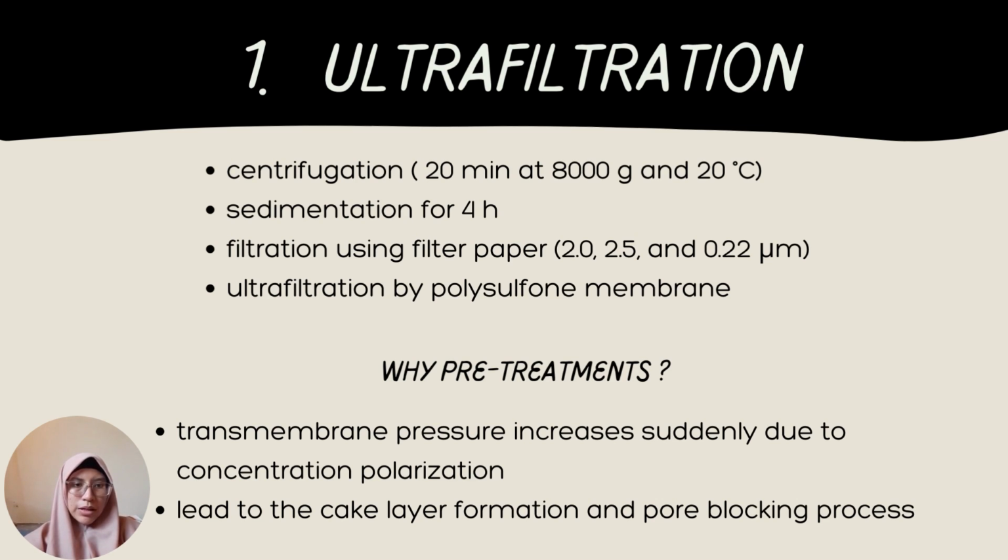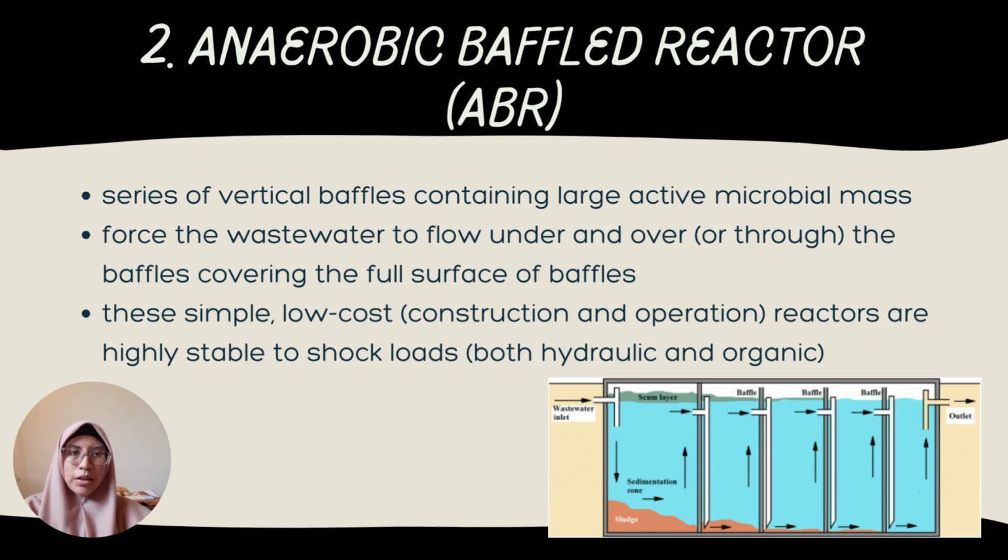So, why these treatments are done before ultrafiltration is carried out is because the transmembrane pressure increases suddenly due to concentration polarization, which leads to the cake layer formation and pore blocking process. Hence, by doing this pre-treatment, it can help in reducing the formation of cake layer. Next, we have the anaerobic baffle reactor, or ABR.